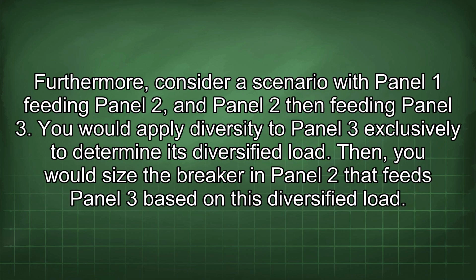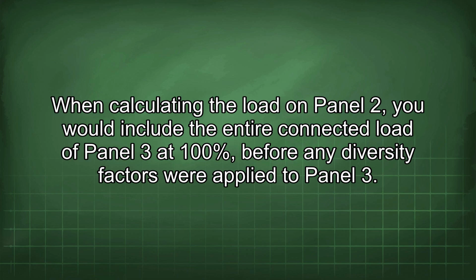Furthermore, consider a scenario with panel 1 feeding panel 2 and panel 2 then feeding panel 3. You would apply diversity to panel 3 exclusively to determine its diversified load. Then, you would size the breaker in panel 2 that feeds panel 3 based on this diversified load. When calculating the load on panel 2, you would include the entire connected load of panel 3 at 100% before any diversity factors were applied to panel 3.